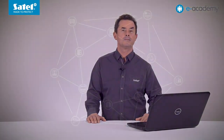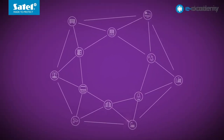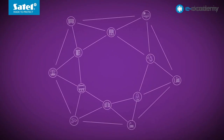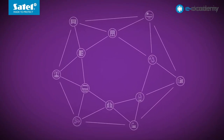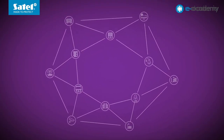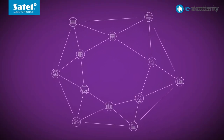To start with, it is worth recalling one of the main distinguishing features of an automation system built in this standard. Namely, that it is a decentralized system. There is no main unit, such as a control panel or controller, that manages the operation of the whole system. The individual devices communicate with each other via so-called telegrams.